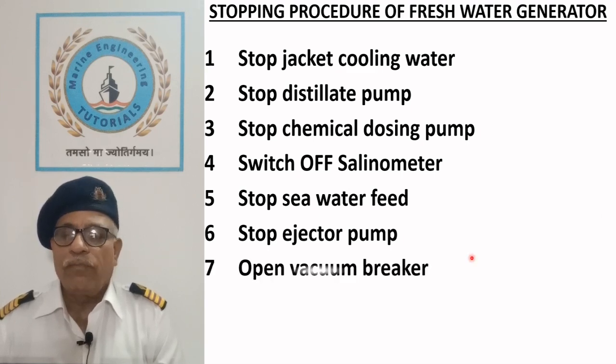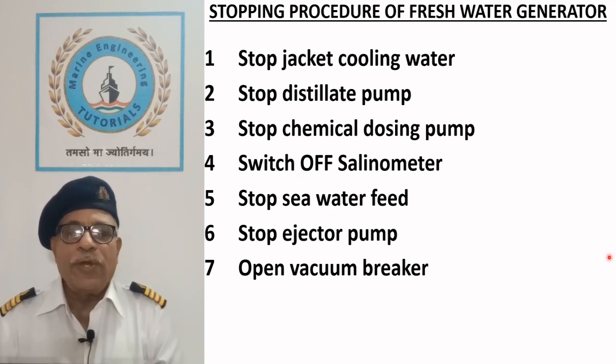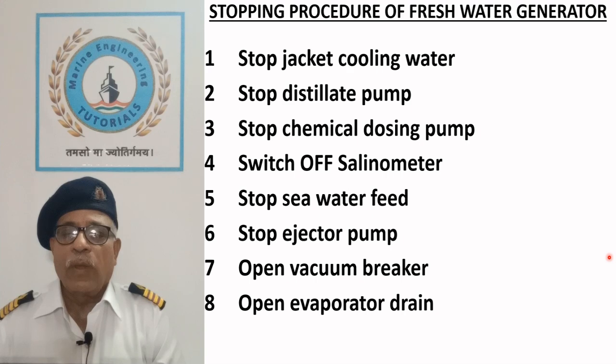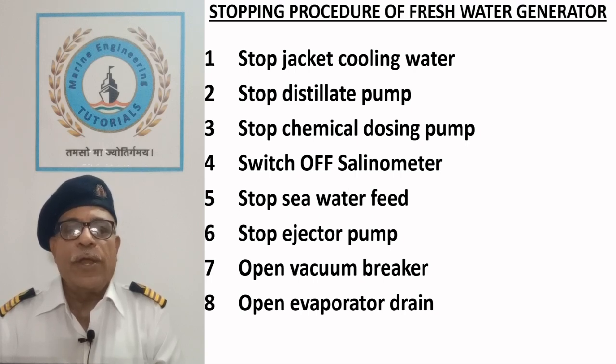Open vacuum breaker. Open the vacuum breaker valve to admit air in the shell. Open evaporator drain. When shell is at atmospheric pressure, remove the seawater from evaporator by opening its drain.